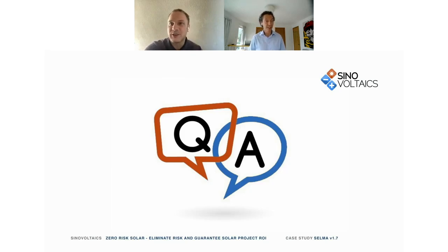Yeah, I fully agree with this. I sometimes have this discussion with other colleagues in the industry. What you look at with this question is basically a mass check of the modules with EL imaging. Electroluminescence imaging needs to happen under certain conditions. With the current technology available, you need to either cover the modules or do it at nighttime. For this, you need portable equipment.